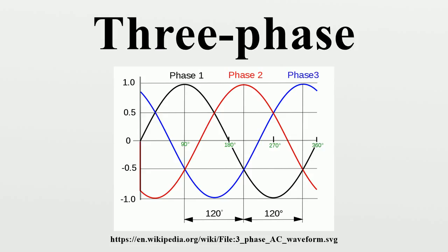Actually, the load need not be resistive for achieving a constant instantaneous power since, as long as it is balanced or the same for all phases, it may be written as so that the peak current is for all phases and the instantaneous currents are now the instantaneous powers in the phases are, using angle subtraction formulae, which add up for a total instantaneous power.